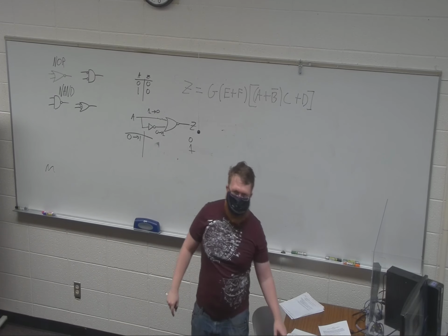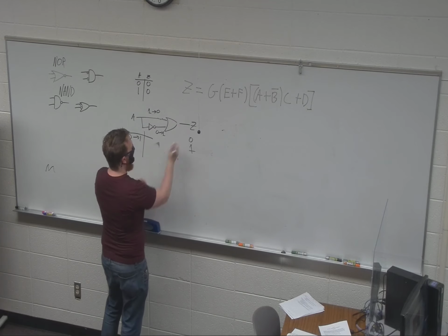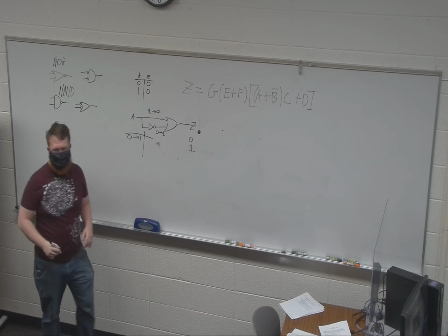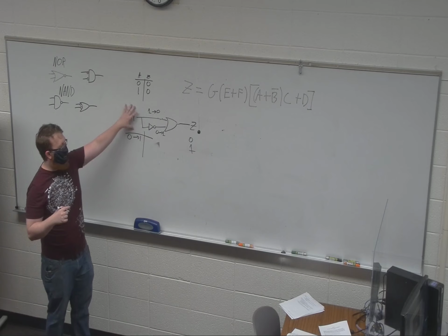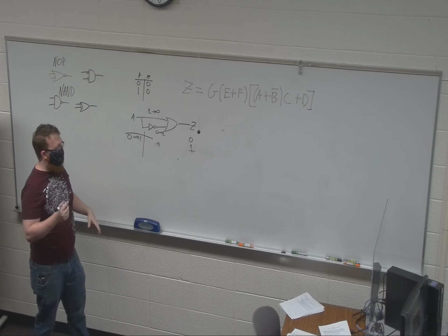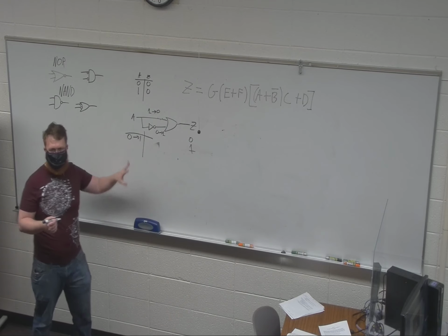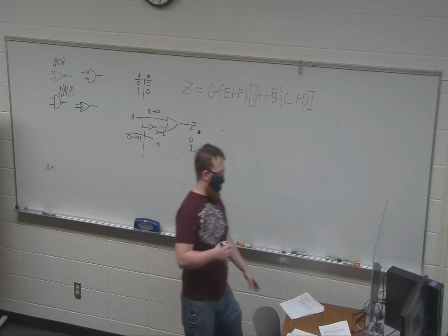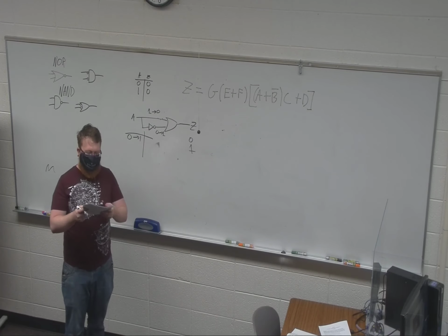So that's your static 0 hazard. Now, if I had done this correctly, like I intended to, and not confuse myself, and did this circuit, it's the other switch that you're going to run into an error. So rather when we're going 1 to 0, it's when you're 0 to 1. Now what's interesting and useful is on a K-map, you can actually see these coming. There's a very literal definition for when this happens, which I will read to you just so we know, and then I'll show you.